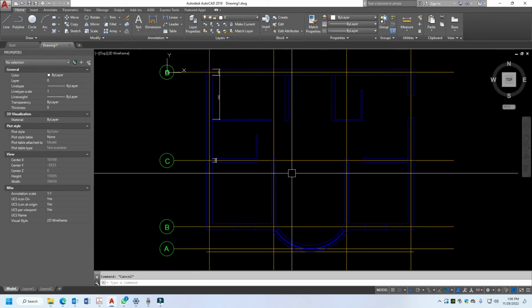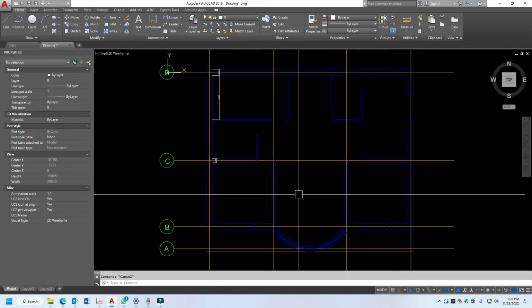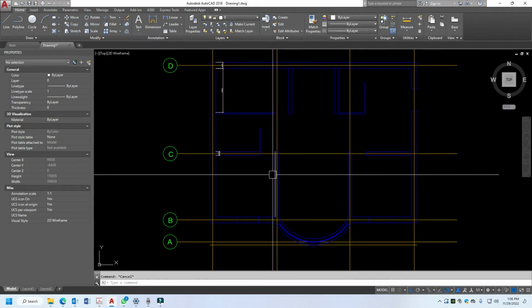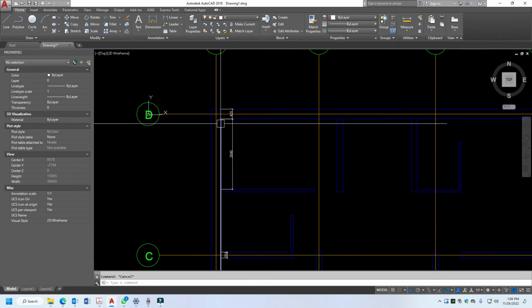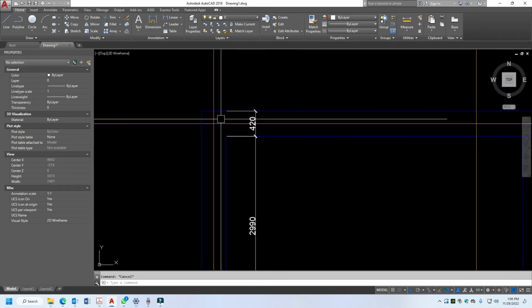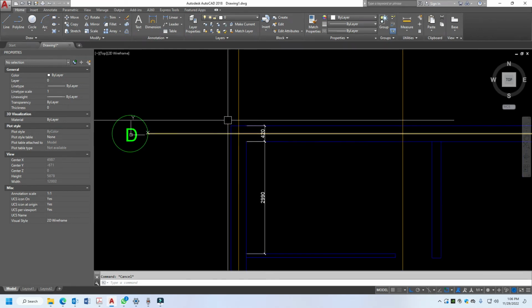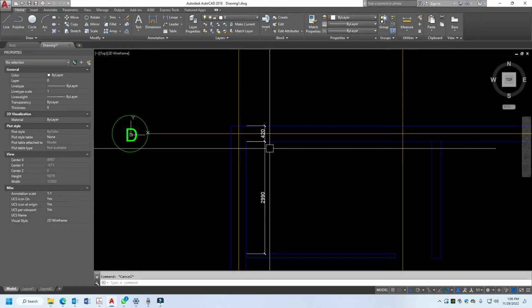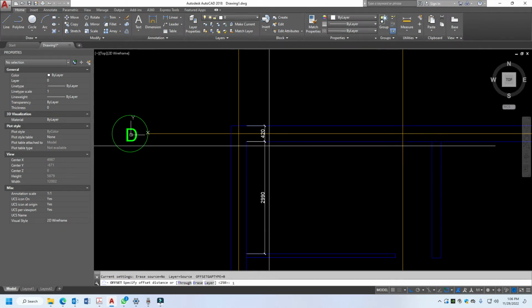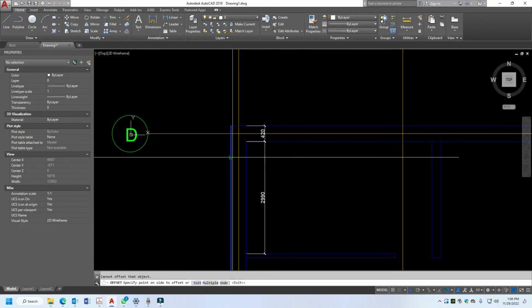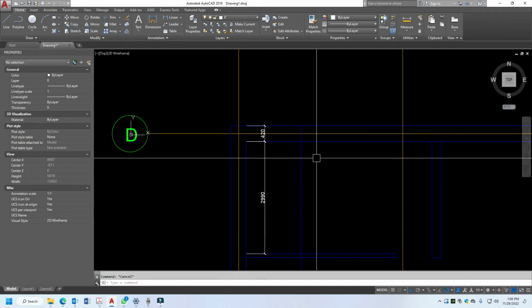This one is all the wall. So you need to have a window. So by creating a window, you need to find the dimension as well. From the corner, which is here, is 1920. So offset 1920. Then offset 15. So this is the window.